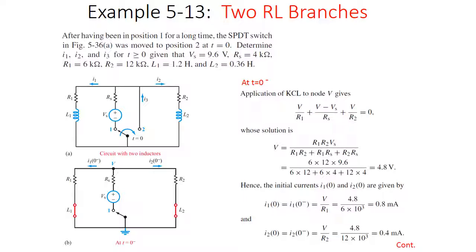So, let's look at A. In A, we have a voltage source with three resistors, because if we look at that circuit, the voltage source is going to push some of that voltage out through that resistor, and then it's going to split down I1 and then I2. Nothing's going to happen in I3 because that's an open circuit, but it's definitely going to split into I1 and I2. So that's going to charge both of those inductors up.